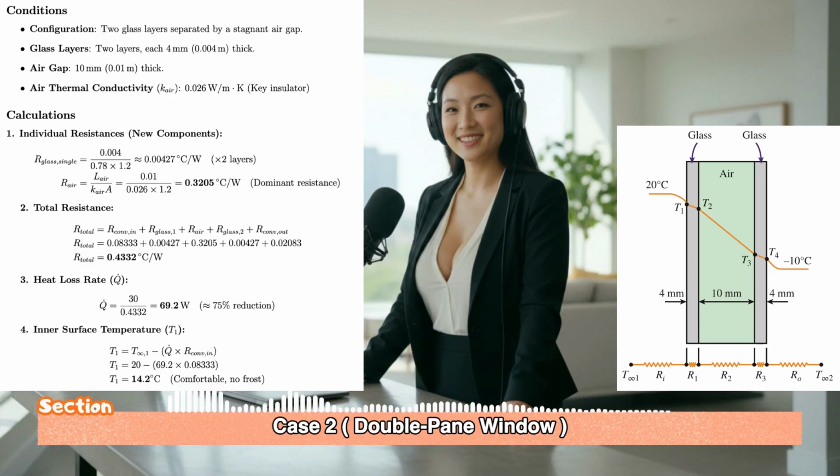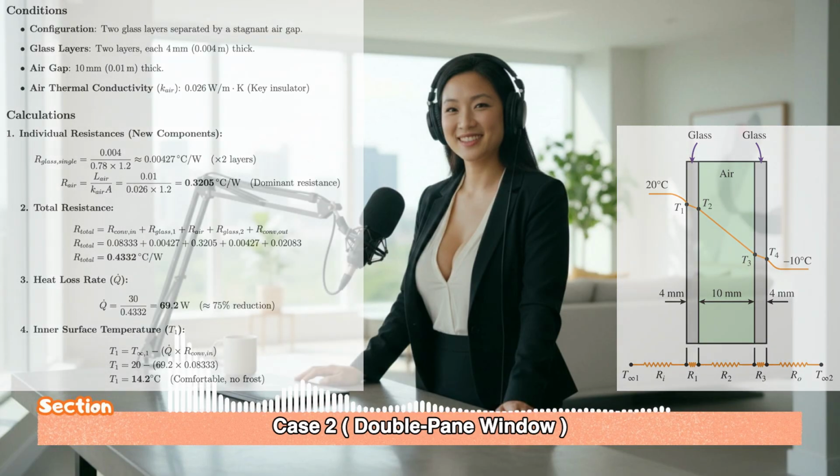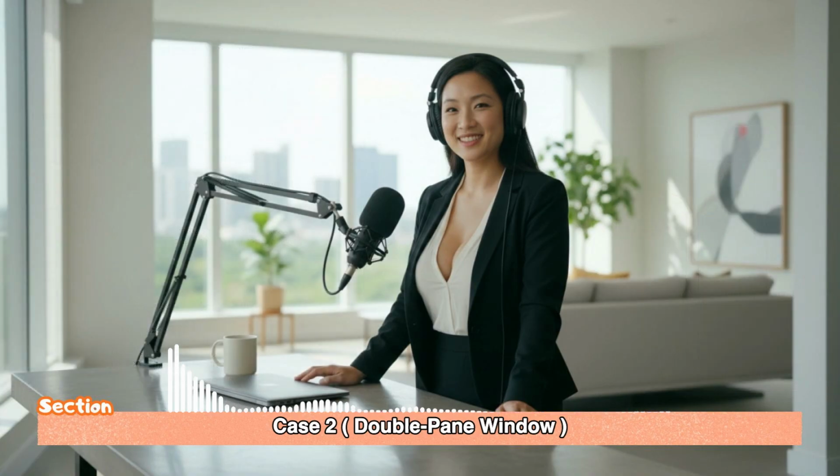Let's check the new inner surface temperature. It's 20 degrees minus the new lower heat loss times the same inside resistance. The new T1 is 14.2 degrees Celsius. And going from minus 2.2 to plus 14.2, that is a massive shift. The surface is now warm enough that frost is impossible, and more importantly, the radiant heat loss from people in the room is dramatically reduced. This one example explains everything about why double-pane windows are now the standard.